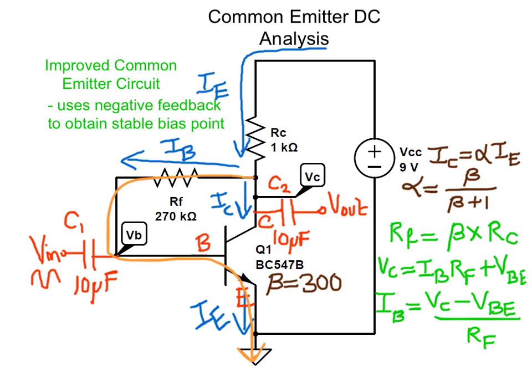So the net result is higher gain offset, in part, by the smaller base current, so that the collector current rises less. We call this negative feedback because the increase in collector current is counteracted. In this situation, the negative feedback leads to reduced amplification, but with correspondingly less distortion at the output.